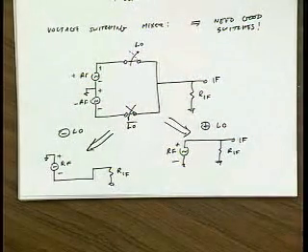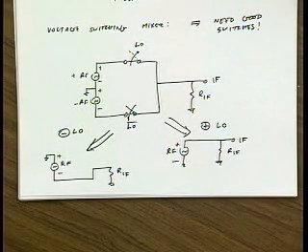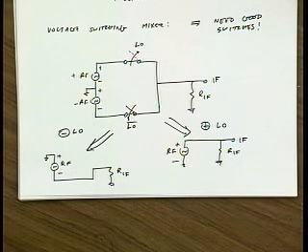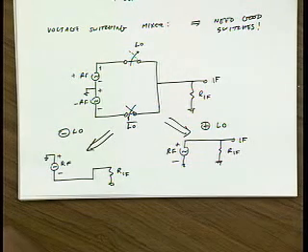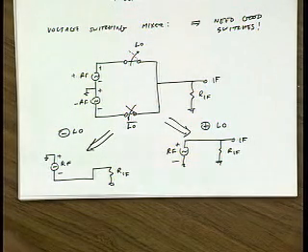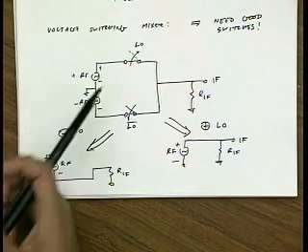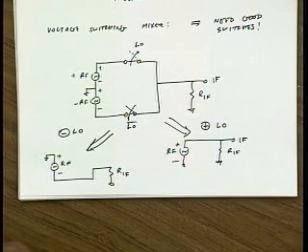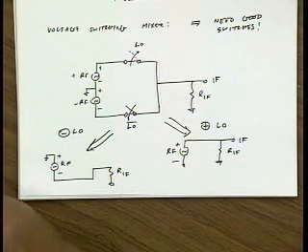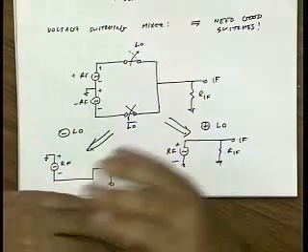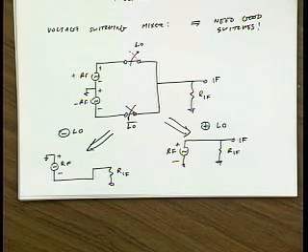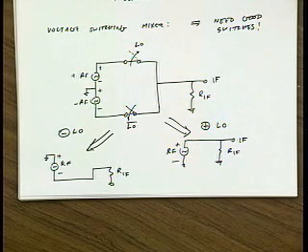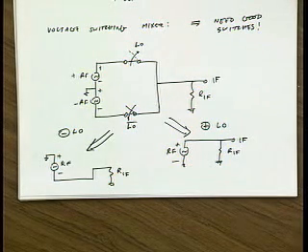Yes, Firas. I mean, MEMS switches are only for like high Q. Do they have other advantages? Are they used for this application? Can we use them for this application? They're not used for this application very widely. One of the reasons is that it's hard to switch MEMS switches very rapidly. We want to switch these things at a rate of a gigahertz. So that's one limitation of a MEMS switch. The other limitation is reliability. There are many ways to build MEMS switches, but if it's something like an electrostatic switch, then you're basically making contact between two metals and breaking the contact a billion times a second. And there's a reliability concern on how many times you can switch a MEMS switch before it fails. So that would be a mechanical mixer. You could build one like that, but they're not really used today.